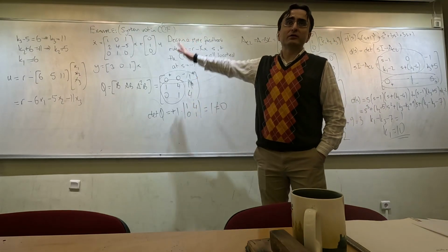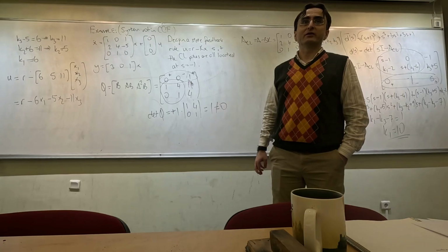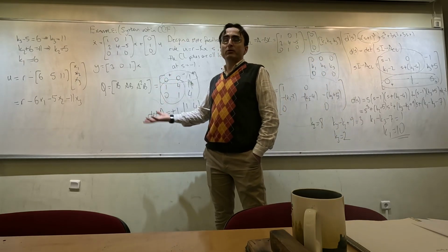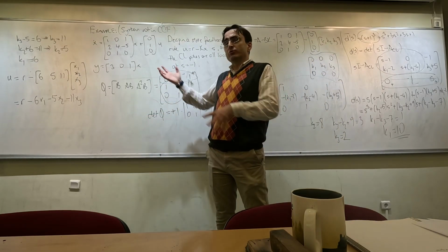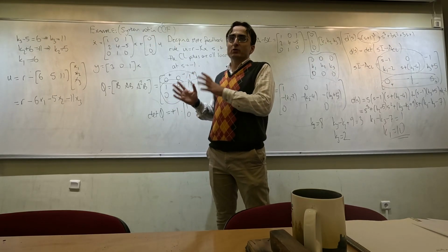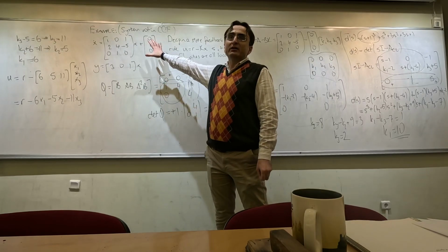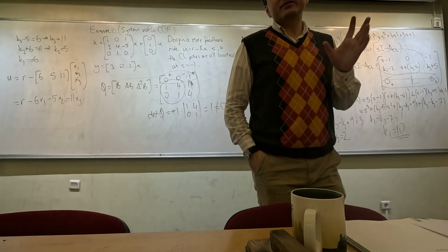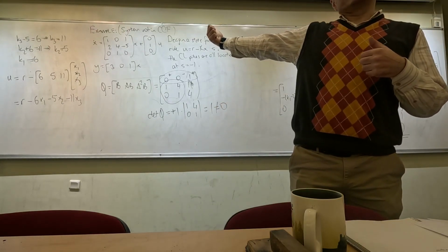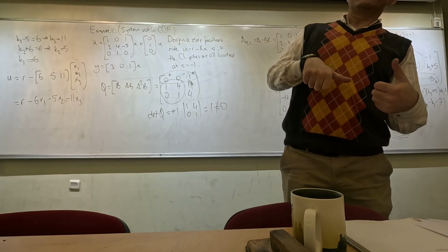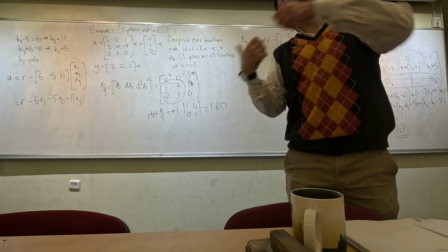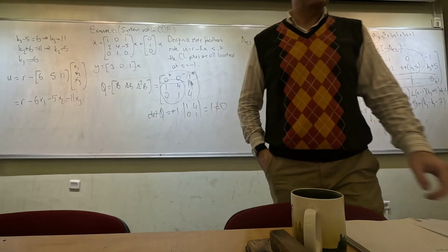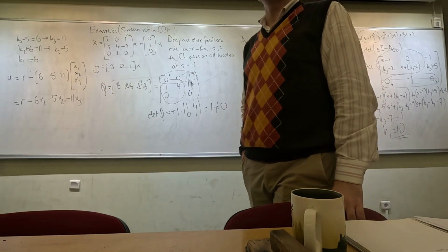You can actually do that with a state, with defining a new state. Okay, so after calculating the transfer function, you can come up with a state feedback gain, and there is also a design. If you would like to do this in a computer, that is what you do. Okay, so when MATLAB gets this state space representation, and if it would like to design a state feedback rule for that, it first converts this into controllable canonical form. It designs the k parameters. Then it transforms those k parameters back into this state space representation. Okay, that is how the computer design is actually made. And for higher order systems, that is the only option.